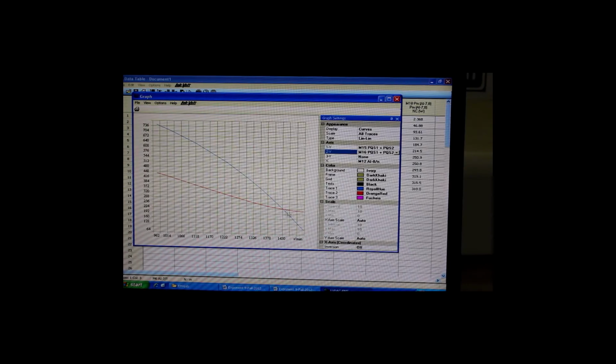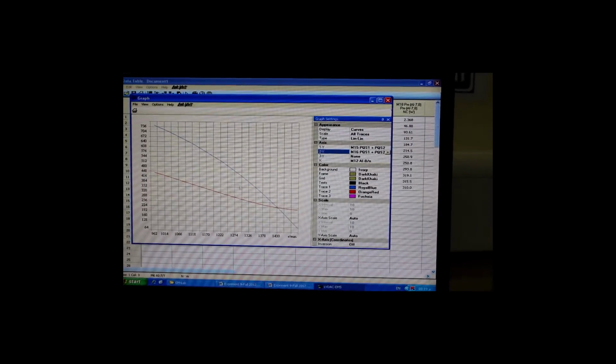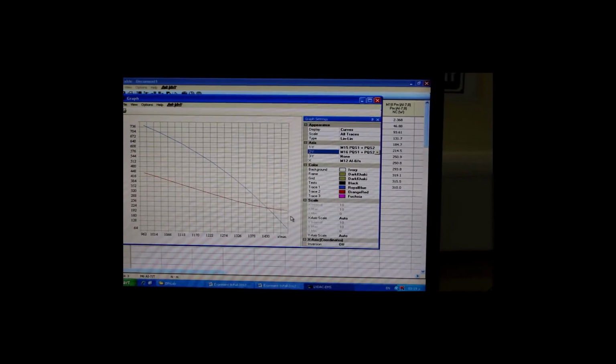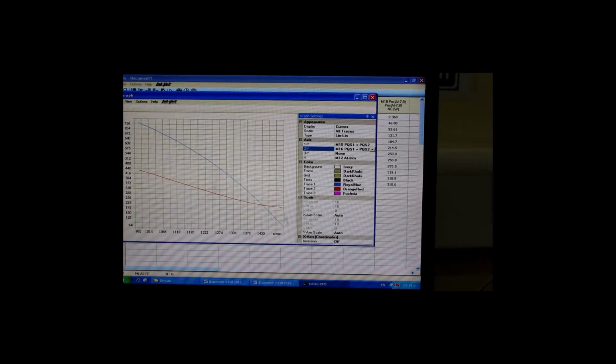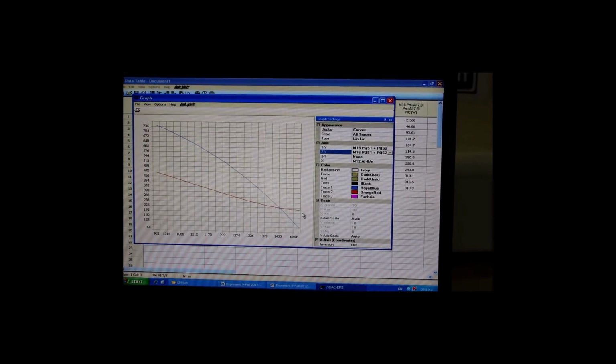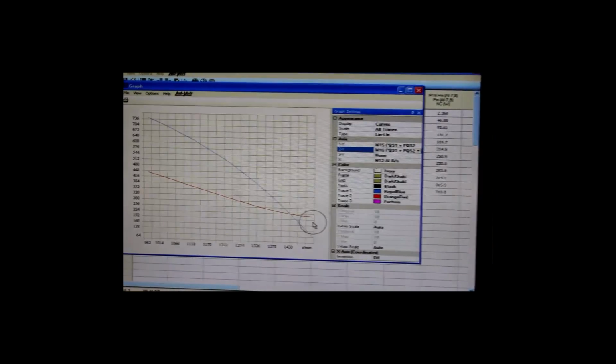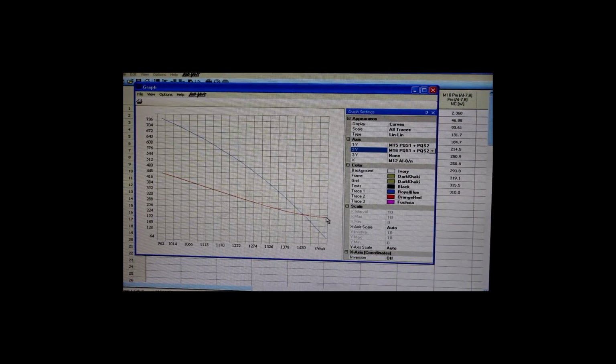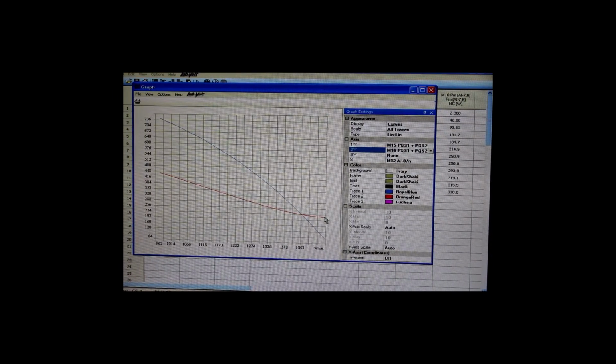It's not constant, but it doesn't change as much as P. You see here in the beginning, we have almost no load in this position. Now P is less than Q, because we always need Q, but in the beginning we didn't need a lot of active power. But then when the load increased, the active power increased, and the reactive power increased, but didn't increase that much.